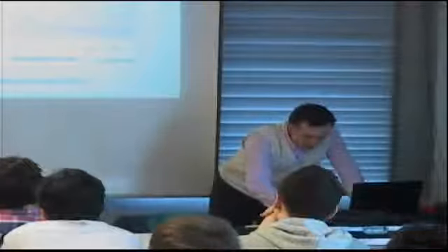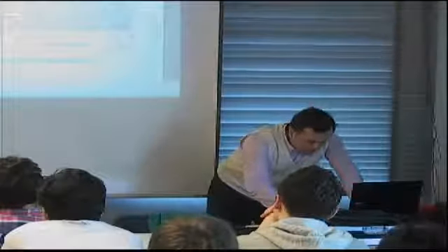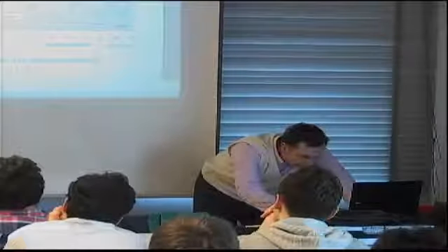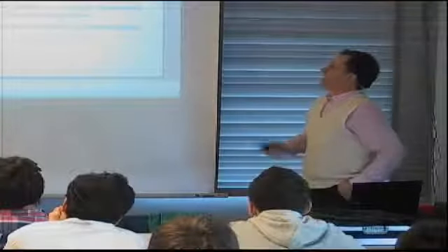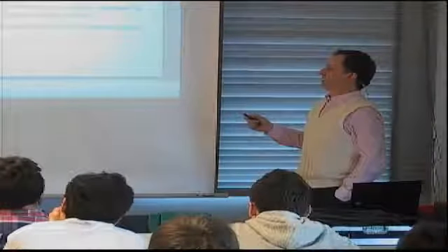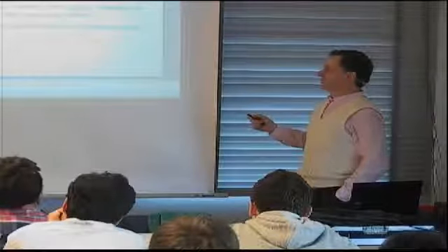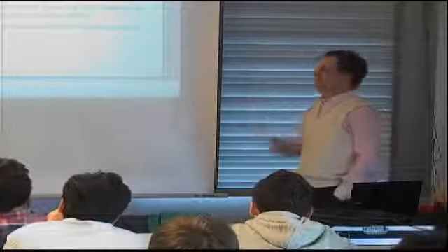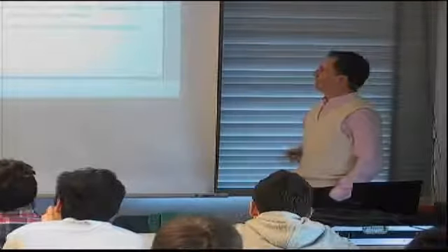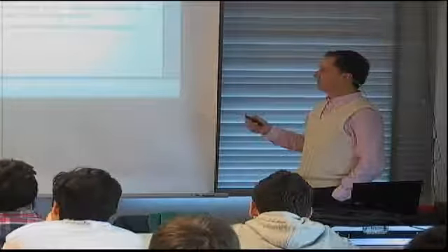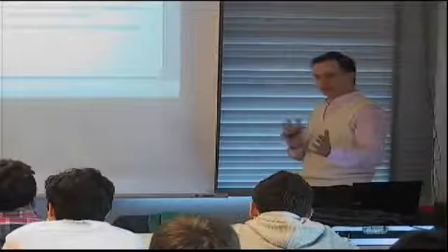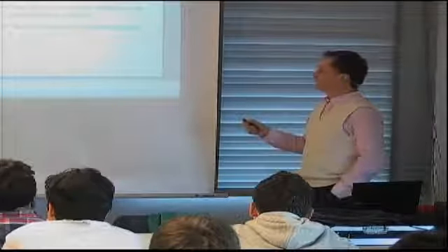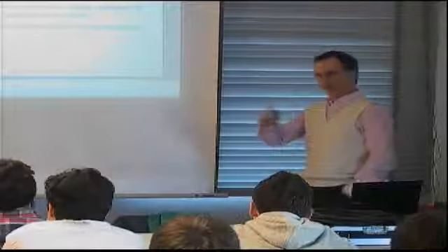Okay, now let me switch to today's discussion, which is more about stiffened panels and crippling again. We will have an example where we will discuss the load between crippling and the load between stiffeners and skin, and the different failure modes. One more failure mode for the stiffeners alone is inter-rivet buckling. Then we will compare inter-rivet buckling with crippling, and there will be some important implications about fastener spacing.